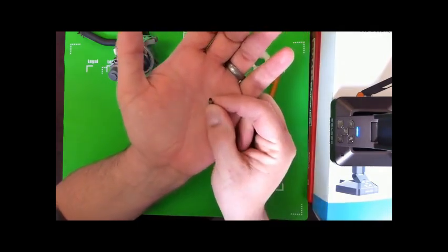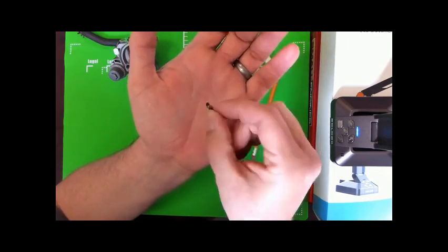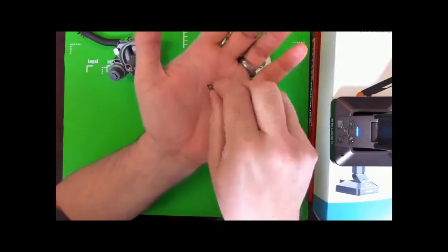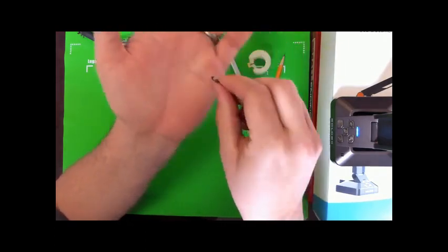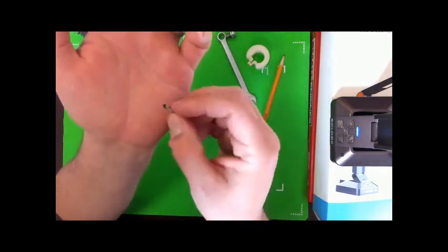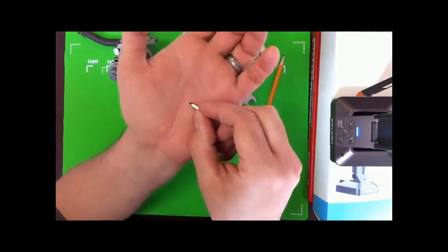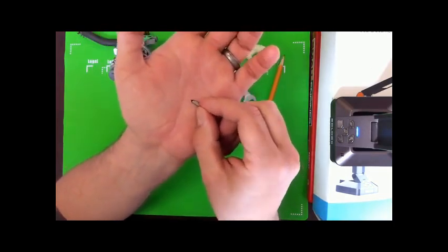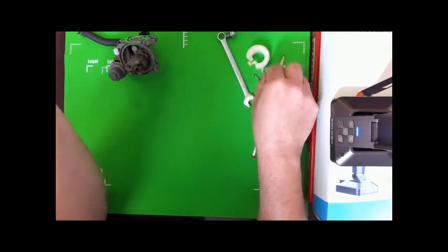It's a good idea to pull this needle valve and check it out to make sure it's a nice sharp point, because sometimes our brass needle valves can wear, or maybe you took the carburetor apart and you dropped it and didn't realize that you bent the tip down a little bit. The rubber ones tend to be either good or not, functional or not.